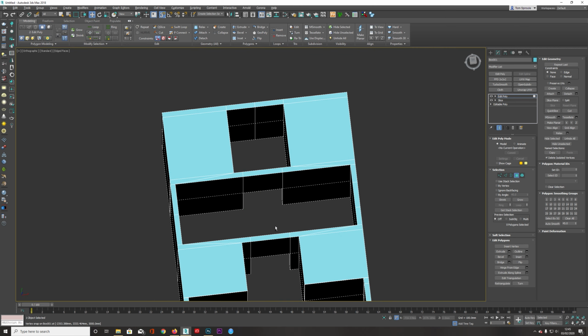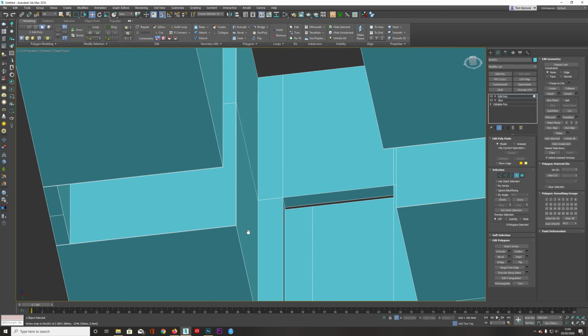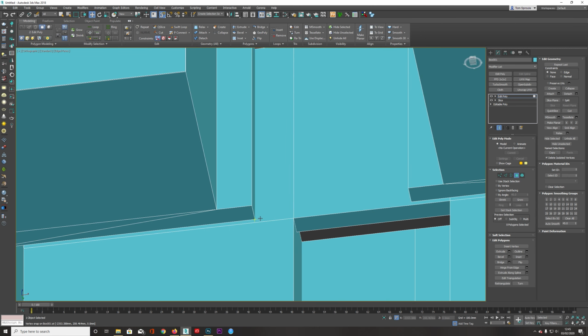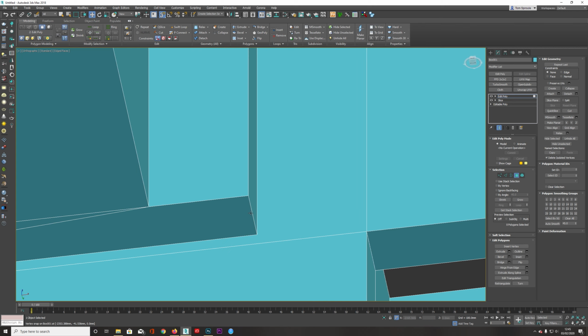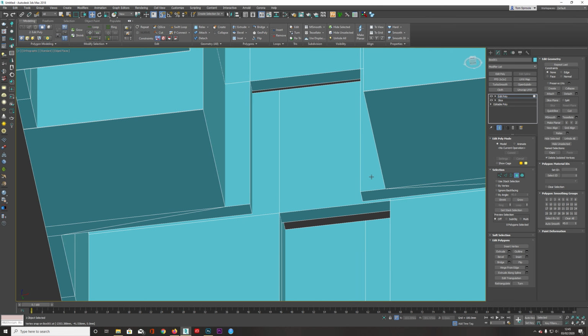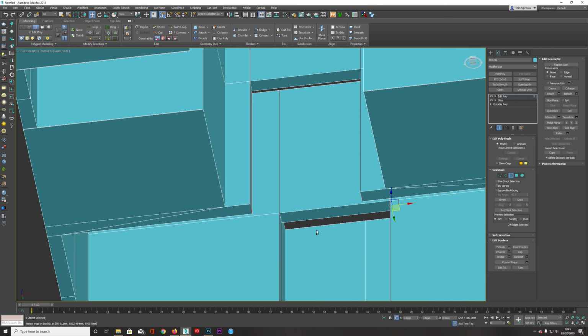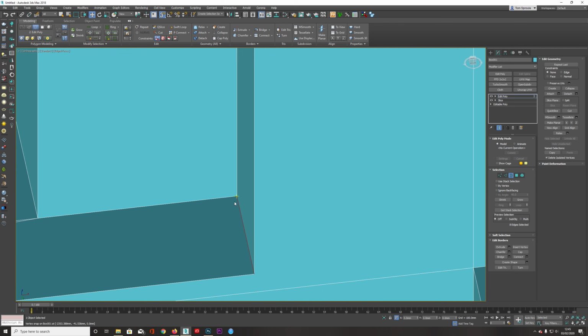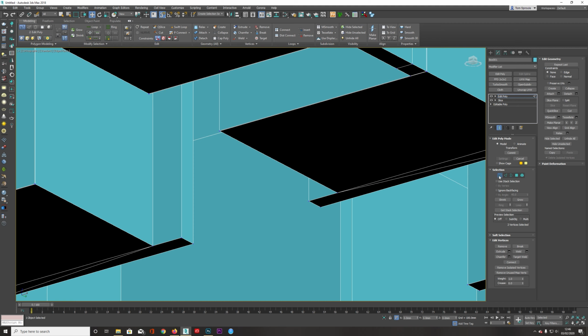But now, in doing this, it's kind of odd because there are now holes in the geometry here, because these were 2 polygons that you deleted. So if you click on 3, for example, and do Control A, you'll see these are red. So that's basically an open face. So what we're going to do is just click on 1, go into vertex, do Control A, and you're not going to see this number change at all because this is 252.